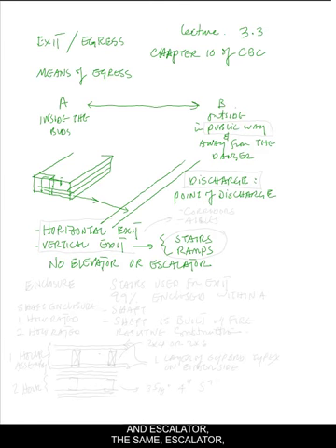And escalator, the same. Escalator, because of the fact that the size of the steps, the mechanical steps changes, and the whole thing relies on a mechanical system to move and not on the ability of the person. So if the electricity is gone, the person cannot move by escalator. And since it changes its height as it comes to an end or on the top, therefore, at the time of panic, people will not necessarily observe that, and it's a possibility that people can just trip.